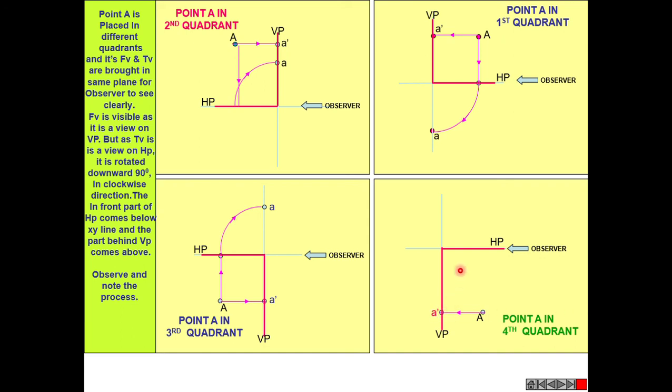And by looking from the top side, I am getting the top view on this horizontal plane. And to convert this 3D system into 2D, we are rotating this plane by 90 degrees. So again, on the vertical plane, the front view and top view will collapse, will collide. And it's impossible to read the front view and top view figures separately. That's why the second quadrant system and the fourth quadrant system are not used in engineering graphics.